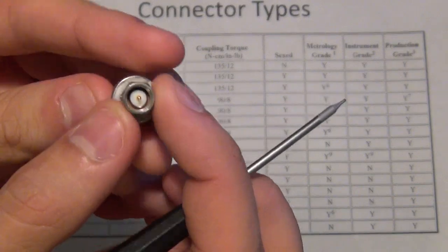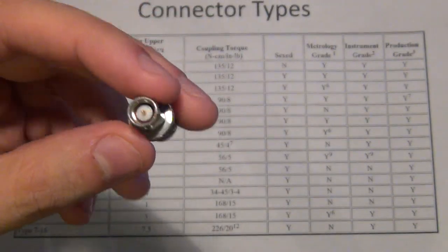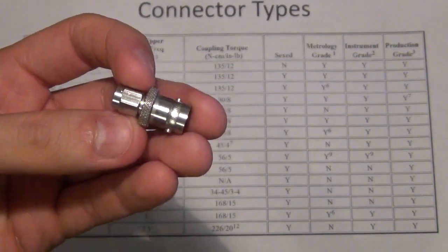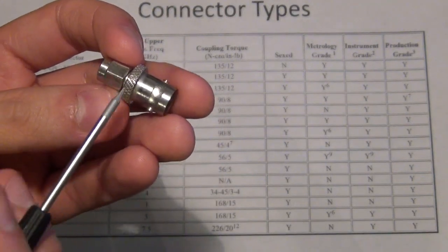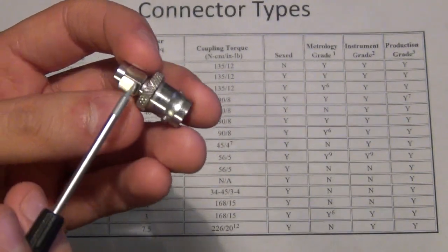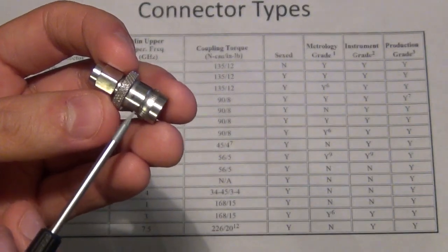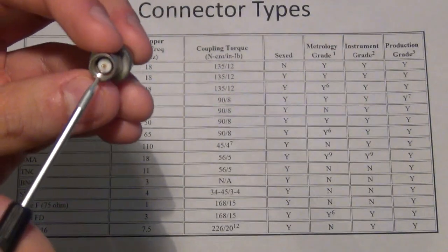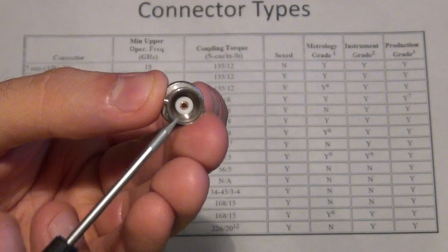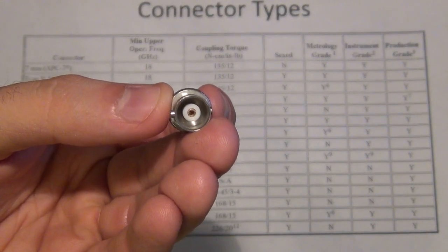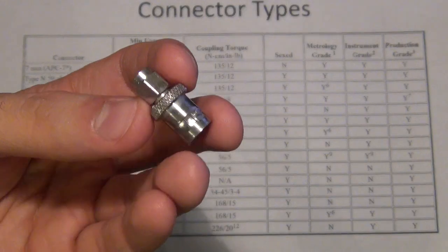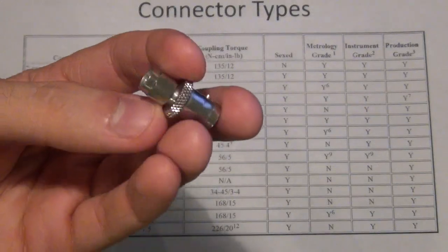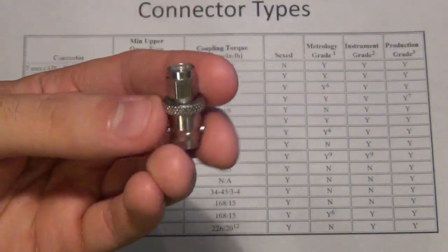This is a connector, of course, and this is actually a converter where it converts an SMA directly to a BNC. Now these type of converters are really common where they go between different types of connectors, and we'll see more of them. But what you have to be careful with is that as soon as you do this, you're limited, of course, by the maximum frequency of operation of the one that has the lowest frequency of operation. So even though an SMA can work up to 18 gigahertz, as soon as you convert it to a BNC, now you're limited to the 3 gigahertz frequency of operation of the BNC, and you can no longer use it above that. These converters are used all the time because sometimes you have something that has an SMA interface, but you need to connect it to a BNC. Of course, all possible combinations of these exist.